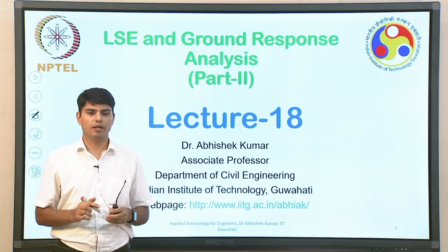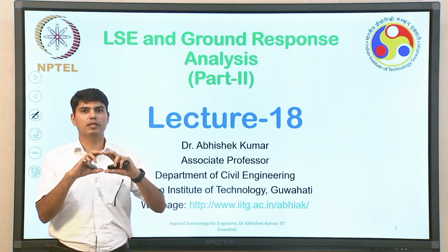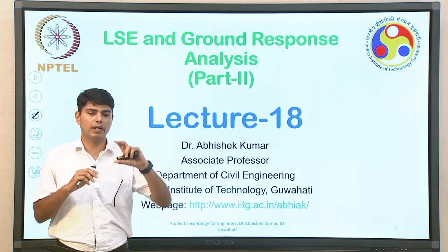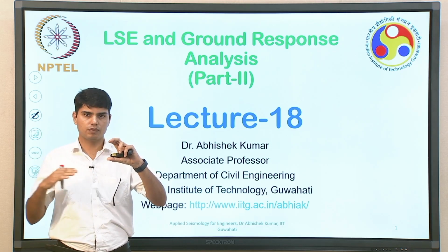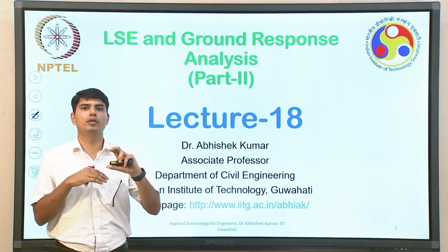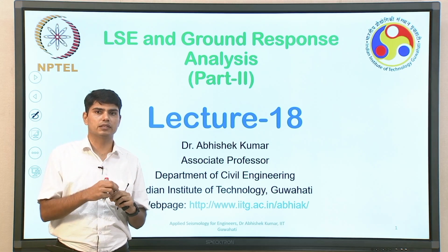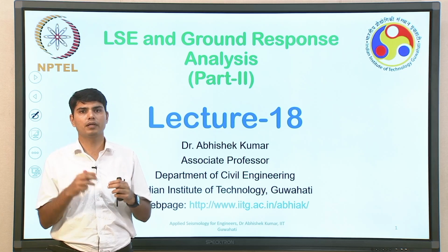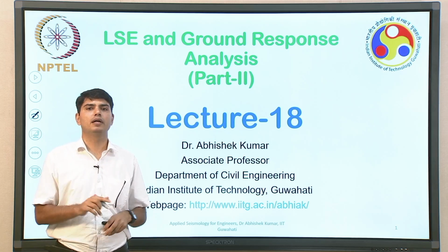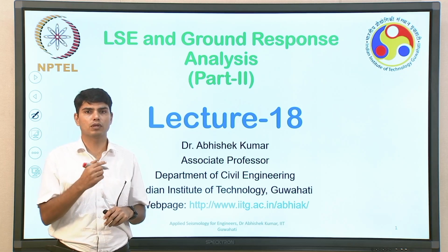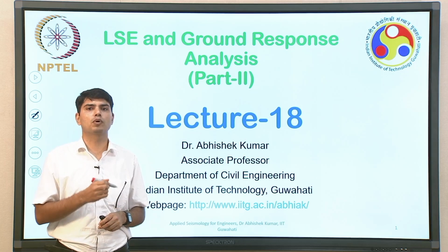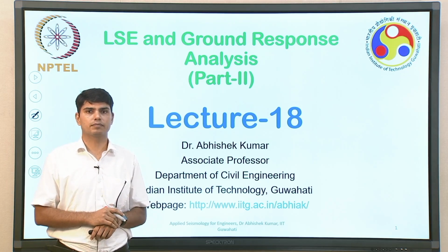What it means is, if there is a soil layer, depending upon the shear strain which is mobilized in this particular layer because of propagation of the shear wave through this medium, that is going to define how much resistance this soil layer is going to offer, whether in terms of shear modulus or in terms of damping, and collectively it is going to define how this soil layer, having one value of damping as well as shear modulus, is going to respond to external loading conditions.